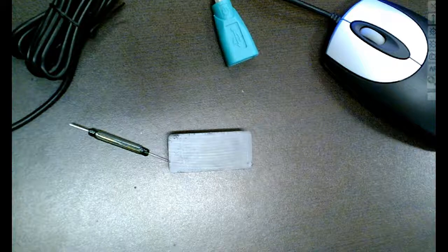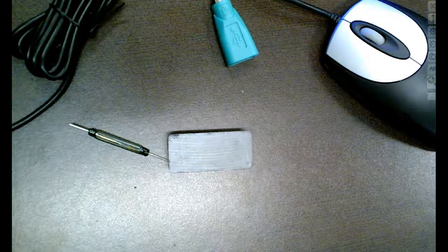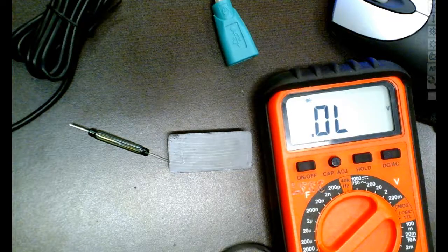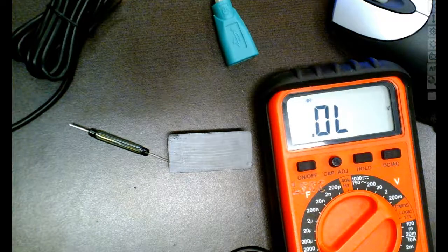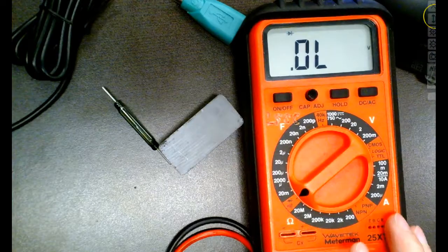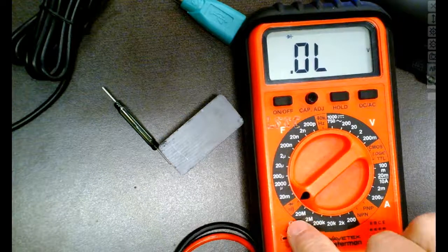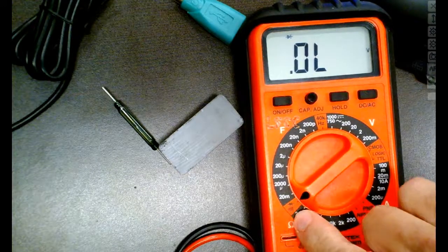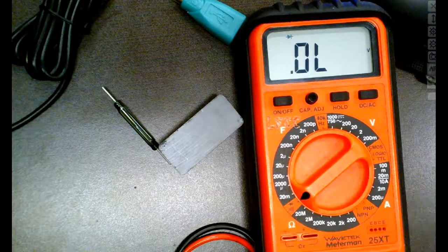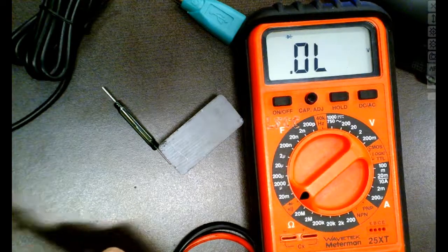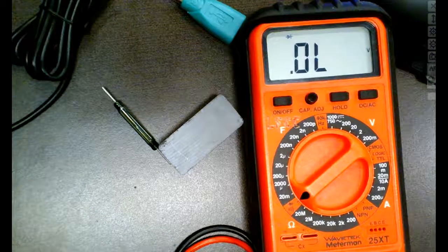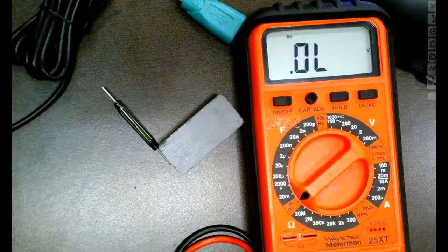So in electronics, we use a term called continuity, and what does that mean? Little or no resistance, usually less than an ohm. Just about all your meters have an ohm scale, and then they have a continuity scale. Normally it's got a little audio symbol on there. What's nice about that is that we can come up here. So that means we have little or no resistance, right? Which in electronics we call continuity.